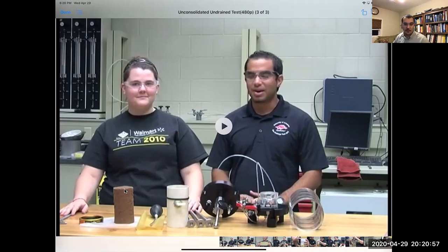And you can also take from your soil sample, originally, a moisture content measurement. Basically, you take a sample and you put that sample in an oven. With that, you can determine the water content before the test and the water content after the test. And you will place the latex membrane on this device right here, and that will allow you to put your soil sample in. So this latex membrane will cover your soil sample.